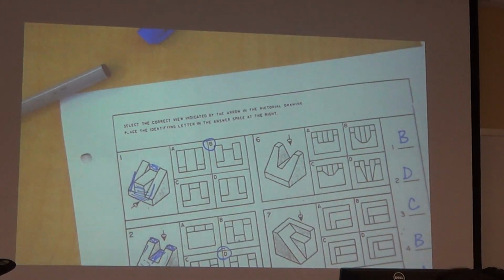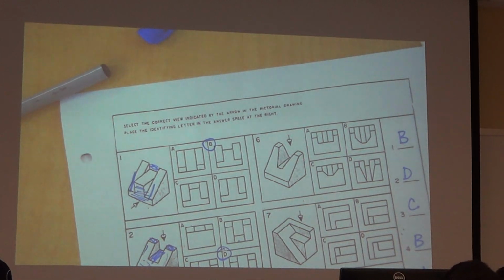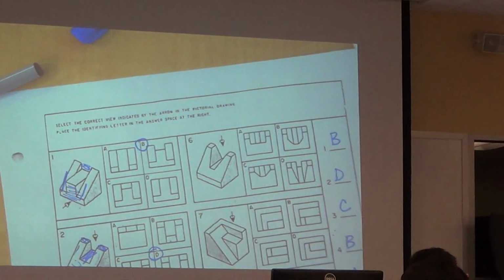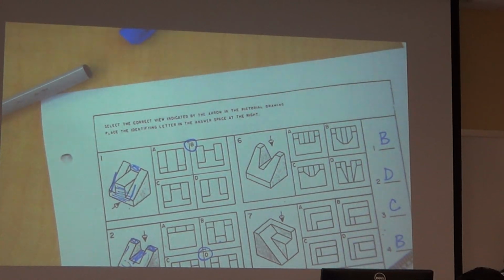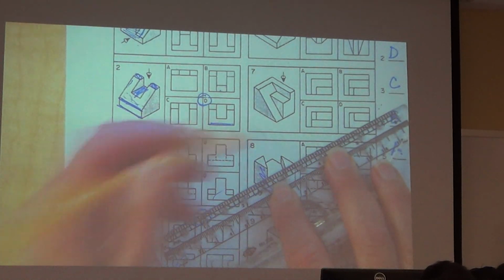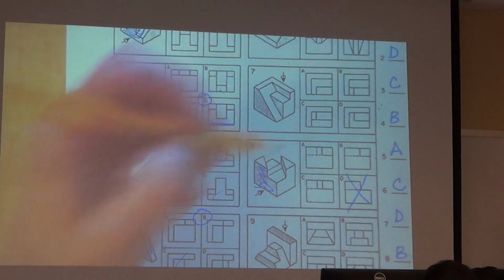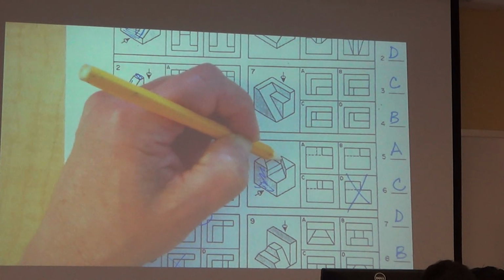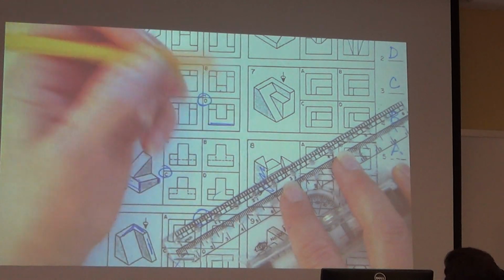Remember when I was over here and I showed that when you do an isometric or an oblique, there are 3 parallel lines, right? 3 vertical, 3 horizontal, 3 like this. It's the same kind of thing, and I'm able to use a rolling ruler, which I'll talk to you about today. So I'm setting up this parallel right here, and I'm drawing this line right here. And they don't line up, so that means down here, this edge is beyond. Do you see what I'm saying?